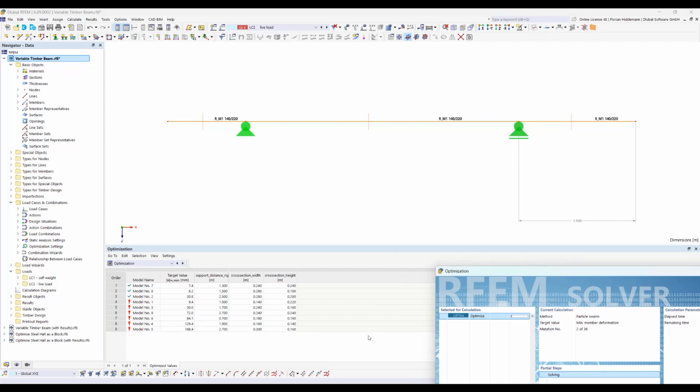This is a small little feature, but very useful if you spend already some time with your model and calculate it, because now the optimization add-on checks each new mutation. And before it calculates it, it looks up into the result table and sees if this mutation was already calculated upfront. If this is the case, we jump automatically to the next mutation without calculating it. And if the model mutation is a new one, which is not stored in the list, the add-on just calculates it and adds it, like you can see here in the background.